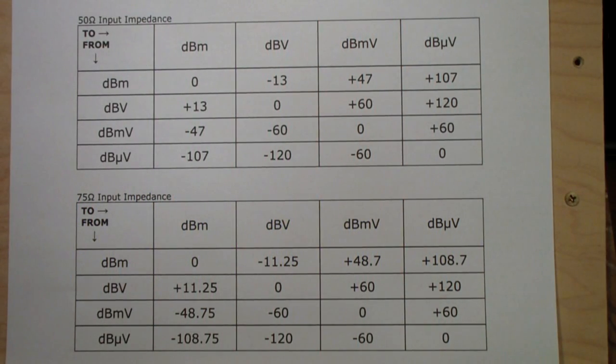In the last segment, I talked about the fact that the Analog Discovery default condition is in dB volts, whereas most spectrum analyzers default condition is dBm. And I didn't mention that the main reason for that, or if I did, I forgot to emphasize it, is that in an oscilloscope, you don't really know what input impedance a person is going to be using.